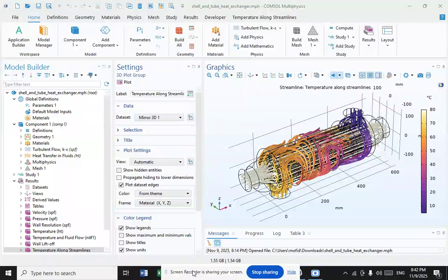And what about the advantages of plate and fin heat exchangers? High heat transfer efficiency, especially in gas treatment, larger heat transfer area, approximately 5 times lighter in weight than that of shell and tube heat exchanger, able to withstand high pressure.